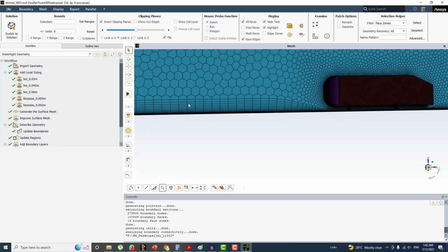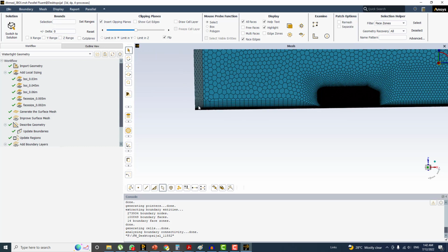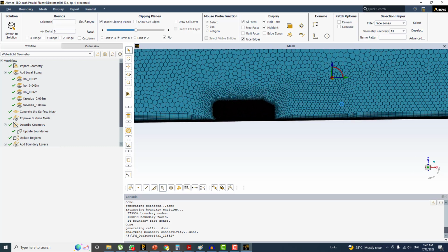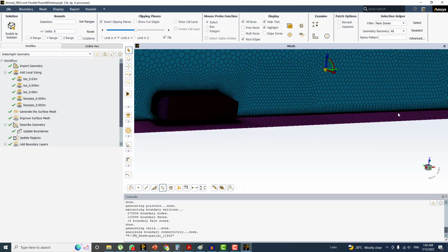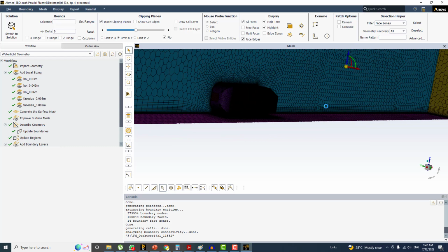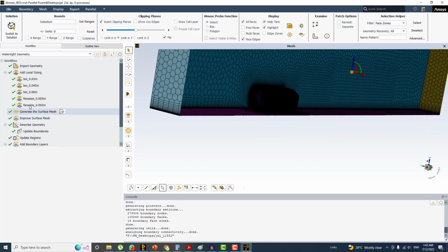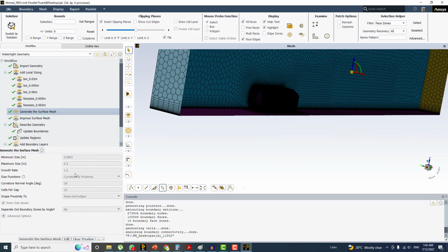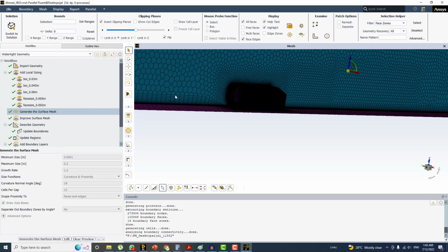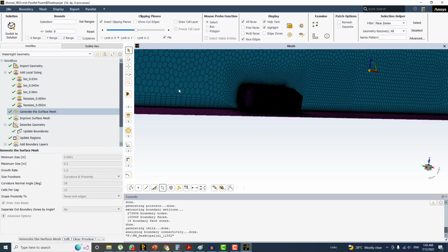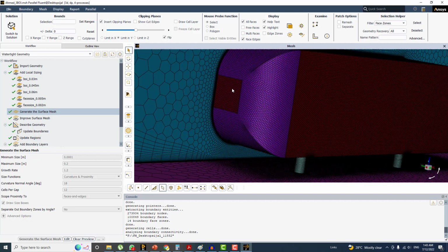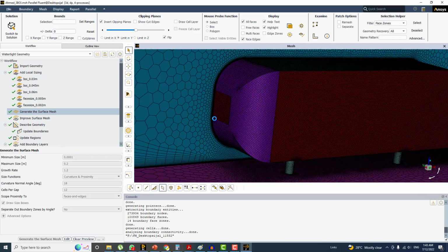Okay, but as it goes to the front side, the size increases because the element size is increasing, and so is the mesh size. So if you limit the maximum size over here, let's say to 0.08 as I did previously, the size of the prism height will be reduced. This is one piece of advice for you.